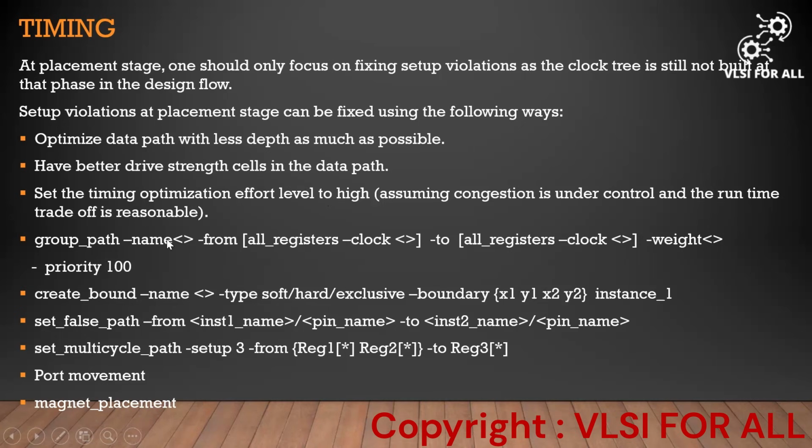The other technique which we use generally is group paths. So whichever paths are violating timing in the setup window, we have path groups like reg to reg, in to reg, reg to out, and in to out. According to which paths are violating, we'll take the start point or end point common to them, and if either is common, we'll provide those paths some weightage.